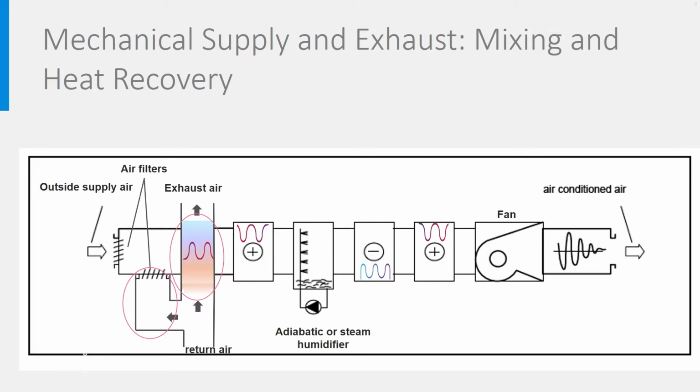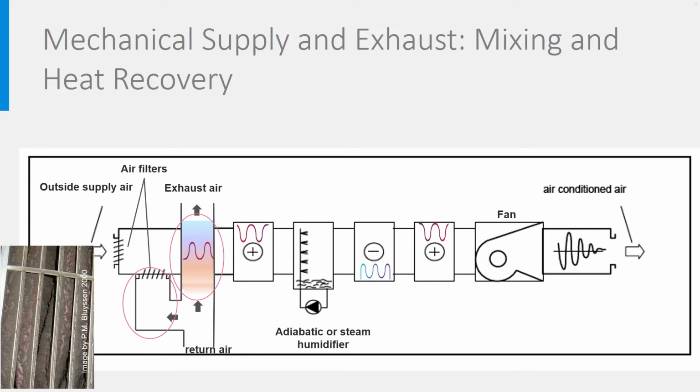Note also that at both the inlets of supply and return air, filters are placed to remove dust particles, meaning that these filters must be cleaned and replaced regularly and kept dry, otherwise they will become a source of indoor air pollution, as you can learn in the MOOC Health and Comfort in Buildings.